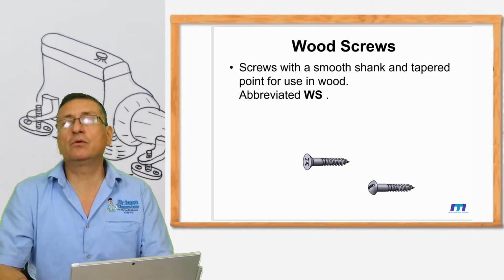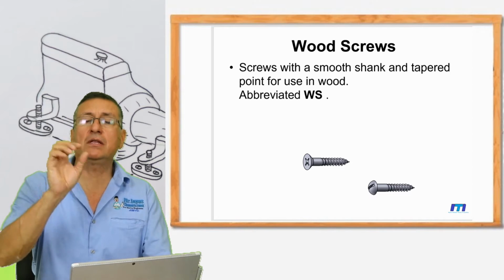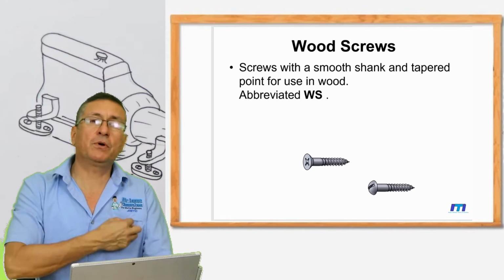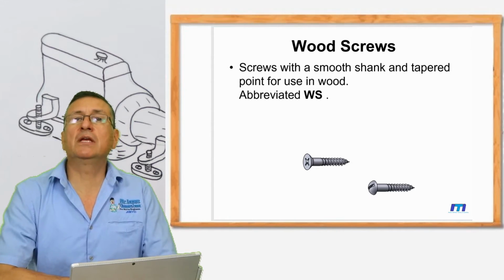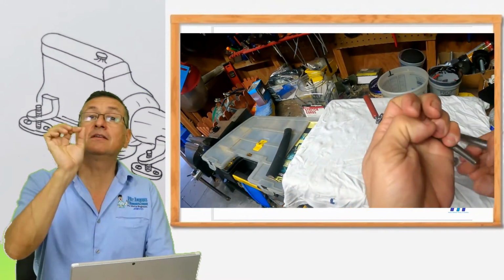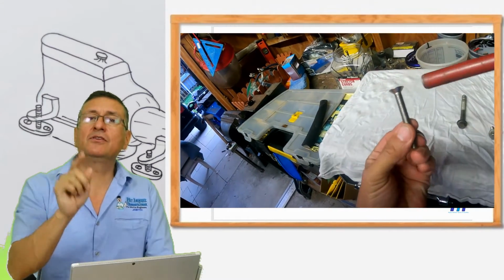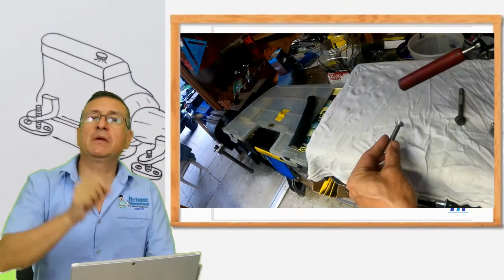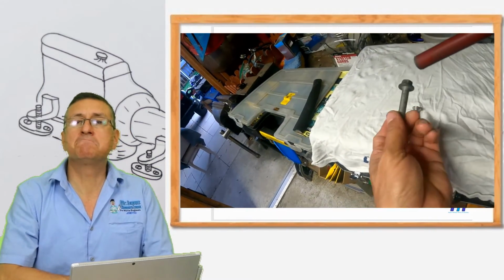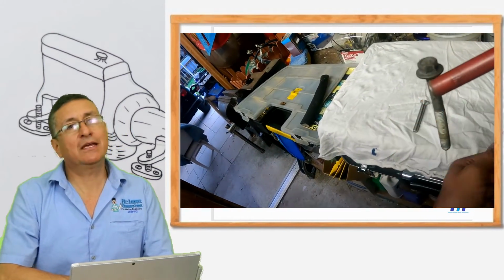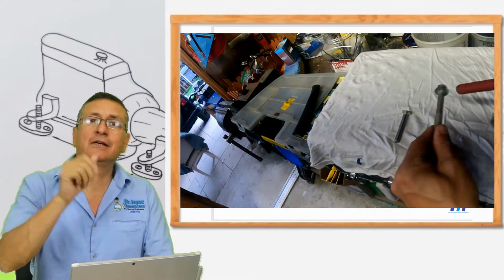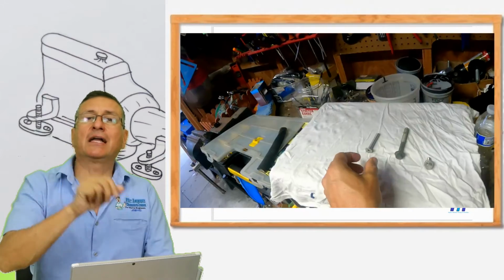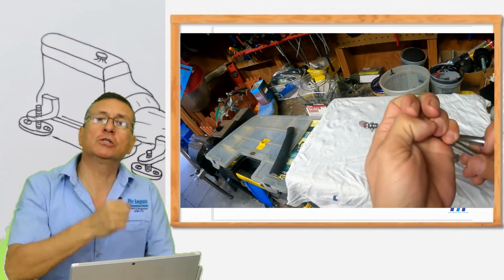If you want to be a great engineer, a great manager in a marina, you need to keep a magnet in your pocket in order to identify if the stainless steel is appropriate. When the stainless steel is good, marine grade stainless steel, when you approximate the magnet, nothing. It's not magnetic. If the stainless steel is medium grade, not properly marine grade, the magnet attracts the metal, and that's not good.